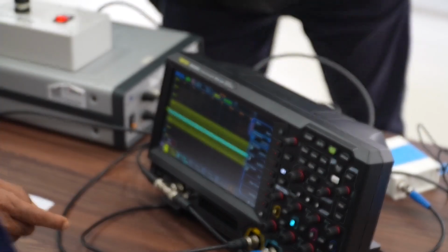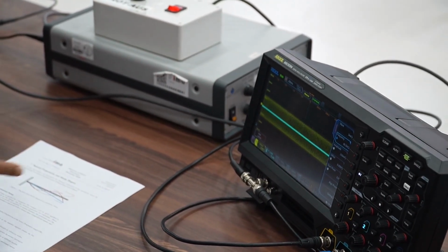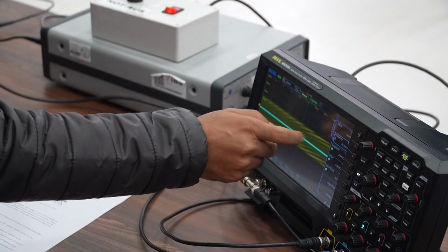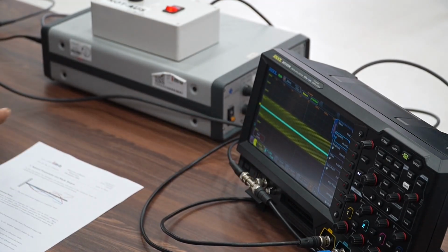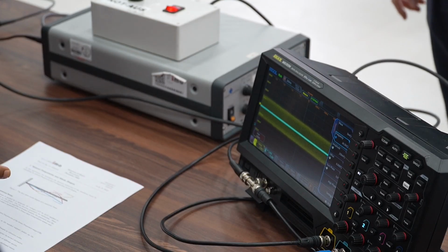Okay, and now what is the frequency? 46.5 Hz. Where do you want to start? With what frequency do you want to start to measure the first eigenfrequency? You should start below and then slightly increase it until you see movement. It is 46.5 something hertz.